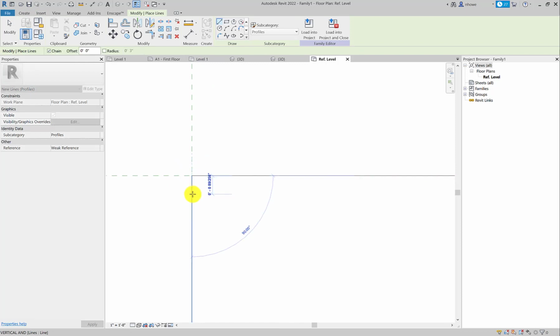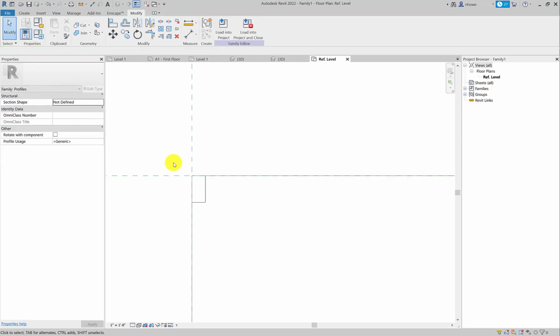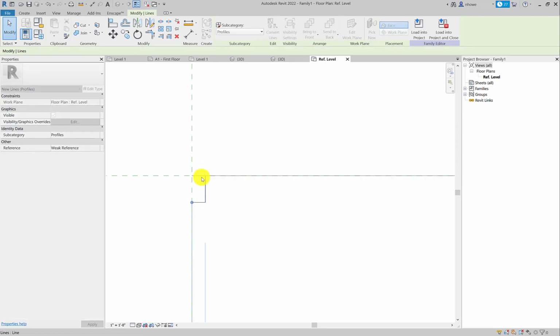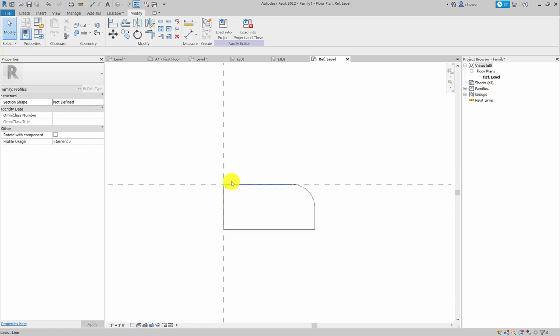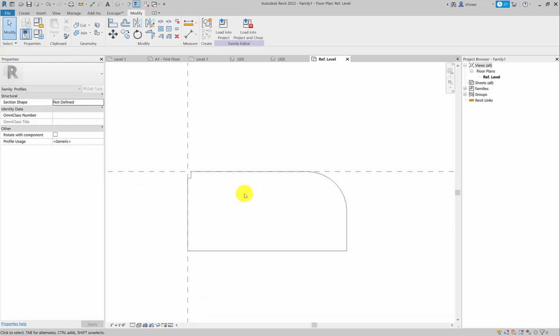let's say I went down 1/2 inch, and then from there I'm going to go over, say, 1/4 of an inch, and I'm going to go up. Now some of those lines are going to basically disappear, and I'm just going to pull back that one and this one. The reason I drew it here is just so I knew what 1/2 an inch was. So that is it. Your profile does want you to complete a closed polyline, otherwise it will error out on you.